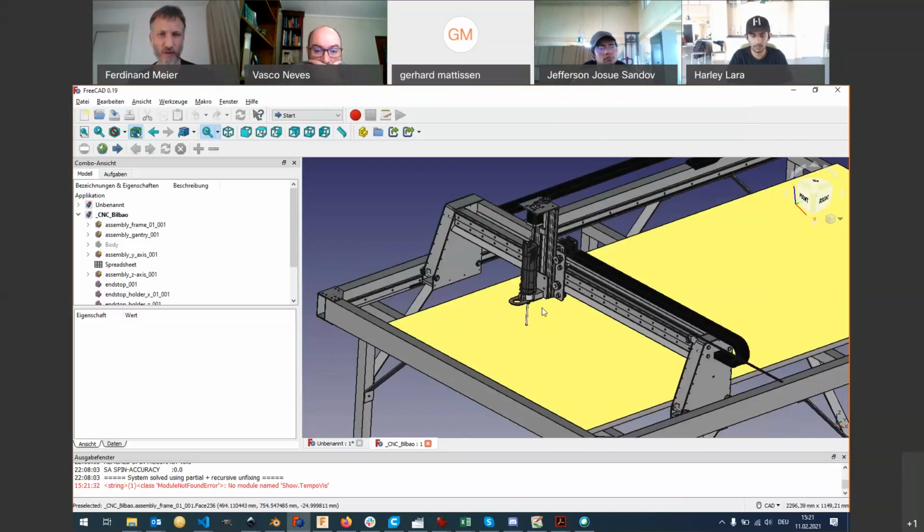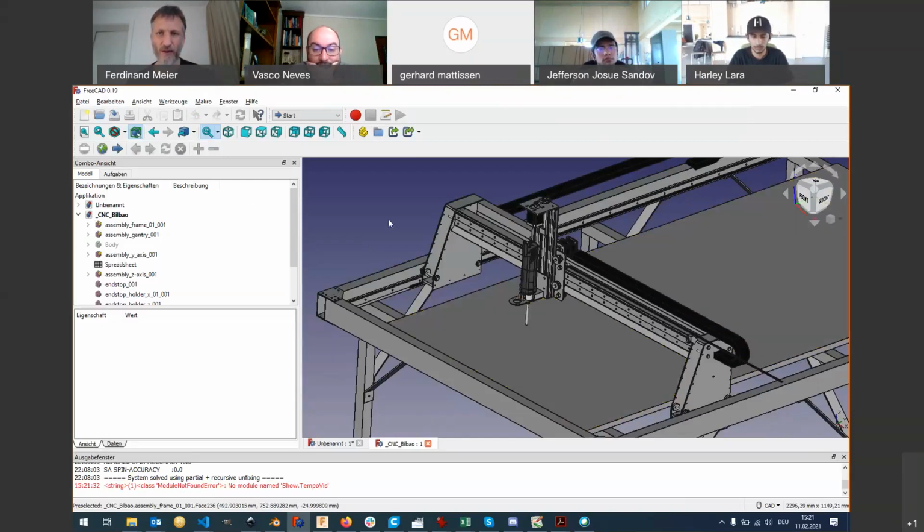And it turns out that even if you take an assembly and rename all the files to .00 and lose all the information, if you name them properly again, everything will fit together again without any problems. So in this case, FreeCAD is extremely robust. As long as the files have the right name, they will fit together.